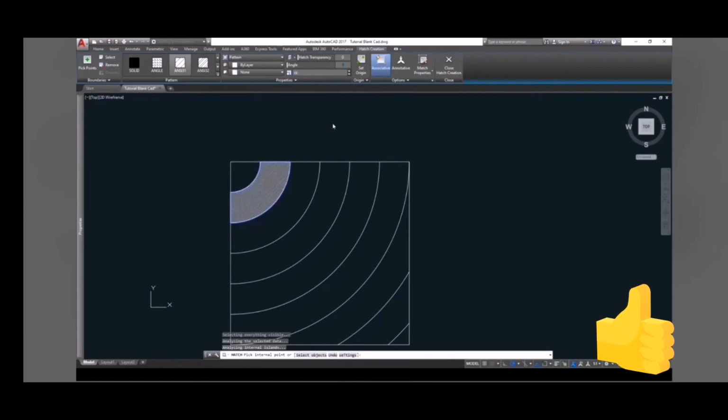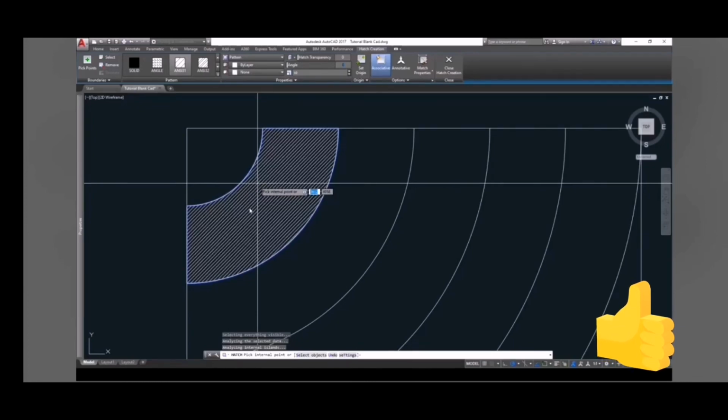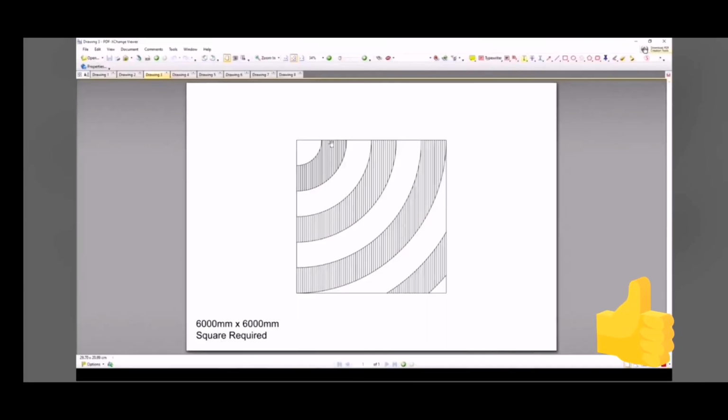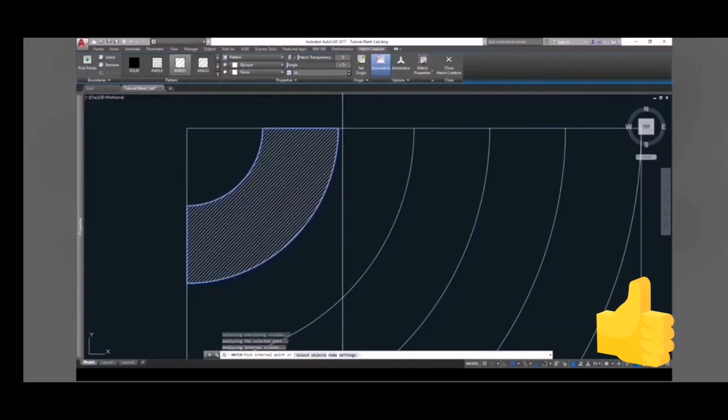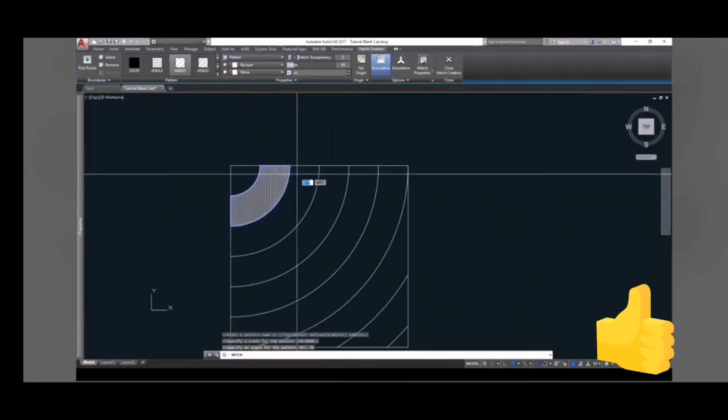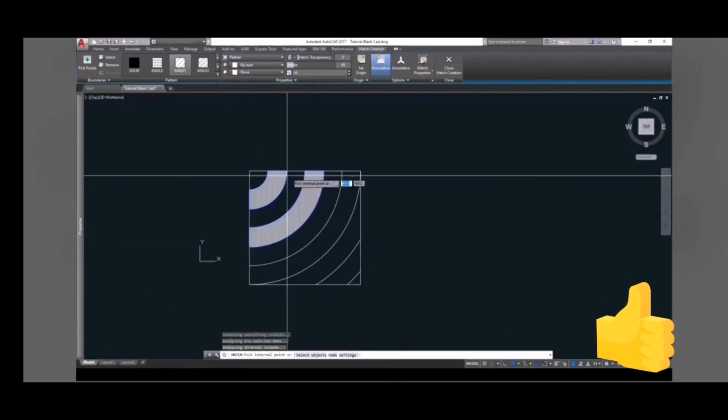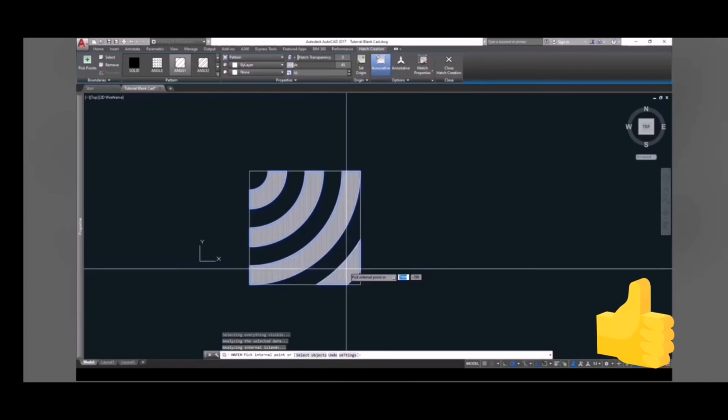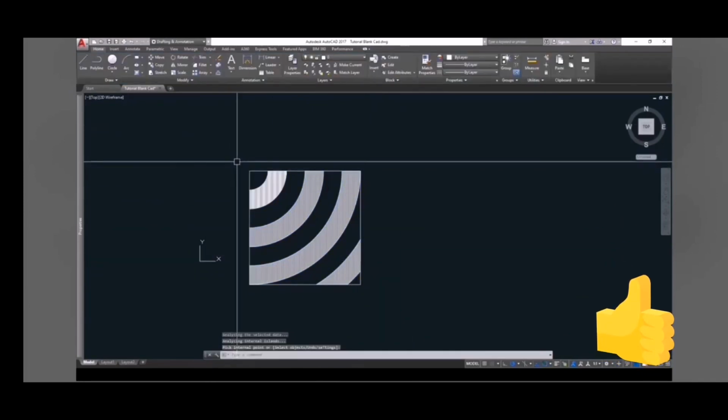This angle is 45 degrees, different from the exercise. You can see here that the hatch is aligned vertically. So now, all we have to do is change the angle input to 45 degrees. Then apply it alternately on the layers. There you have it, we just have finished drawing 3.